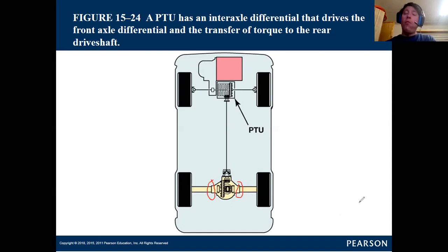So if I have one tire spinning a little too fast, I can let that clutch pack slip a little bit while still giving the other side 100% friction lockup and transfer some of that power to the tire that actually has traction. Front to back, it can happen in the same regard. If I have a viscous coupler in line with the rear drive shaft, I can apply or release torque to the entire rear end of the vehicle.